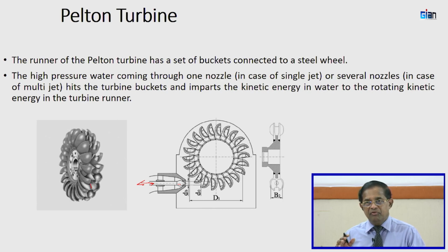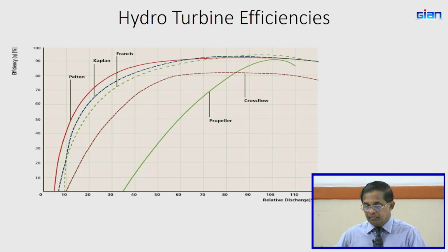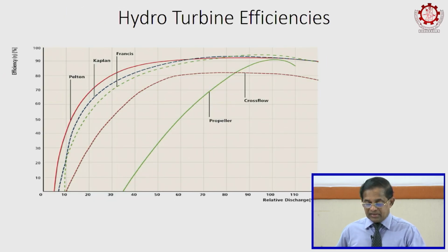They make very small plants, maybe 50 kilowatt, still with buckets separately made and welded or bolted. But for large machines, 200 kilowatt and above, they always cast one piece and then machine the buckets, right? Here I think we discussed this elsewhere as an answer to a question.